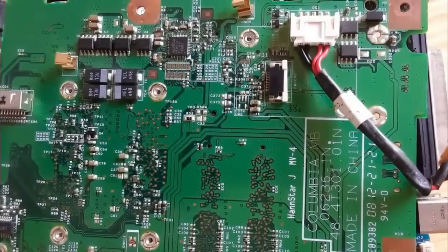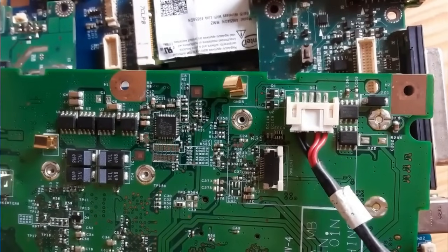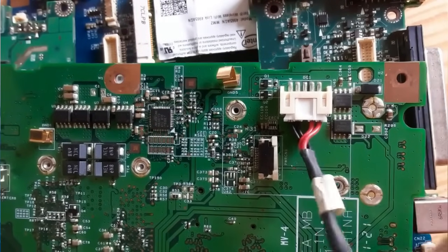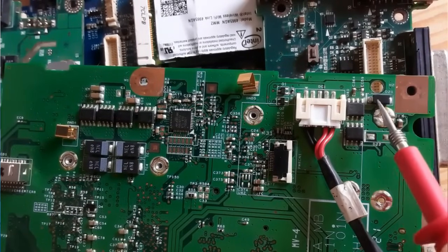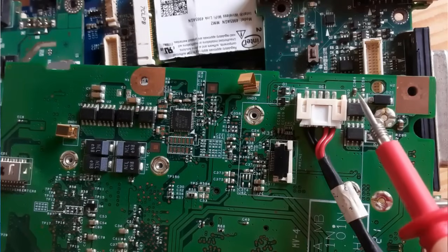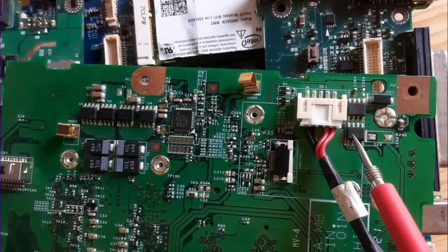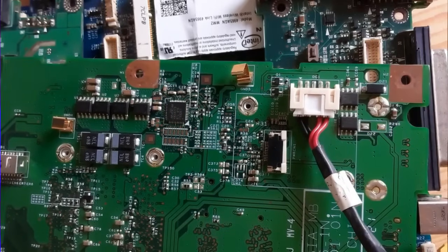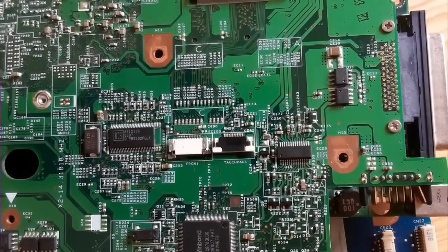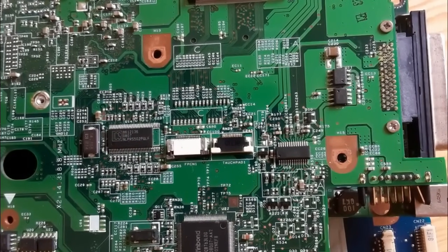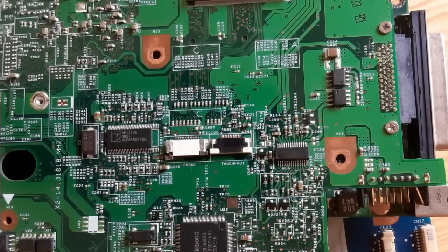This is another motherboard. Of course, I will show you many kinds of motherboards in order to go deeper into understanding what I'm showing. Here we have the power jack connectors, switches, and the diode. This is the power circuit. Normally the charge IC should be next to the power jack, but if you don't find it there, you should check the battery connector. Here we have the power IC.